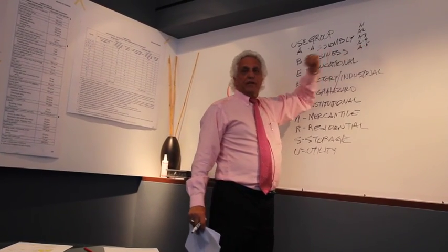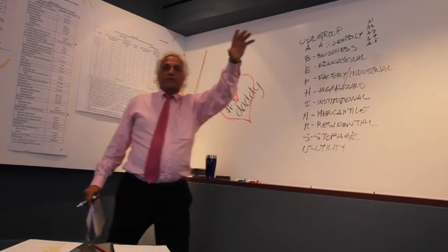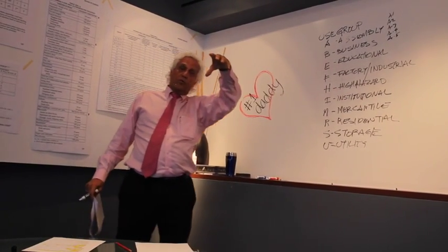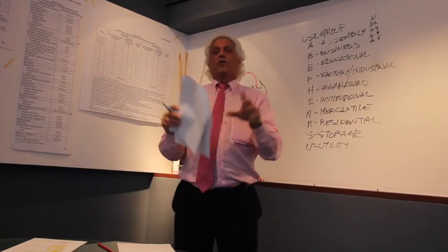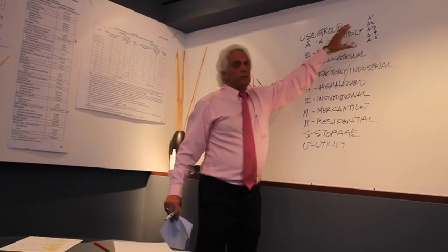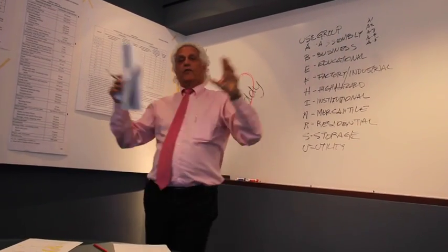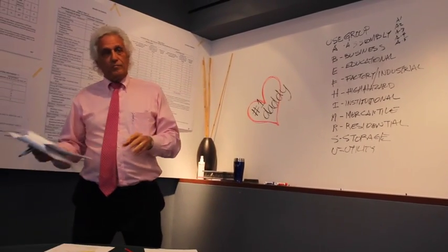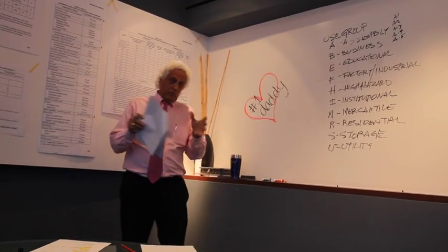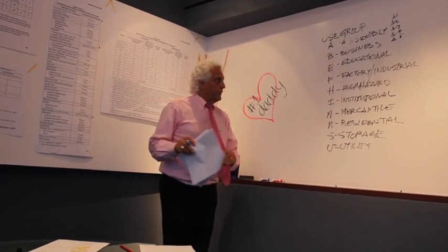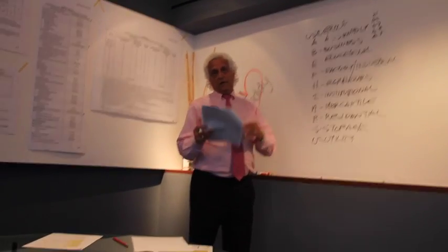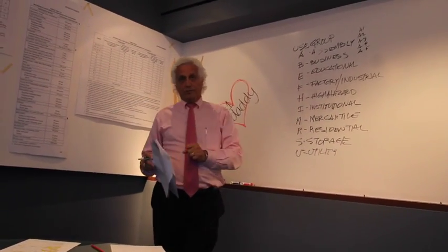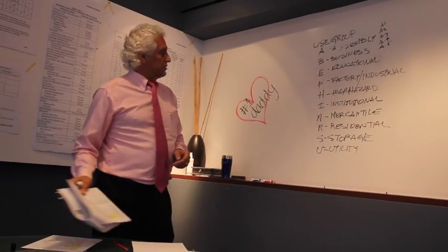You have movie theaters, you have stadiums like Ford Field that are enclosed or under one category, and Comerica Park that are open, they fall in another category. But those are assembly, and those are typically reserved for a very large number of people. Usually the magic number is 300, although you can have smaller numbers of people in assembly uses. By example, restaurants. A lot of restaurants have 100 or so people, maybe 150. So that's an assembly use.